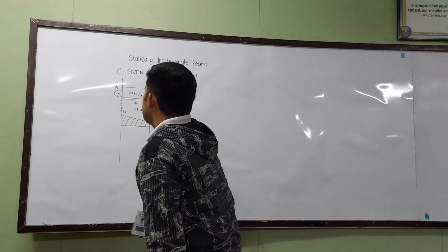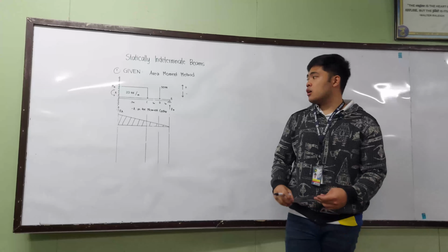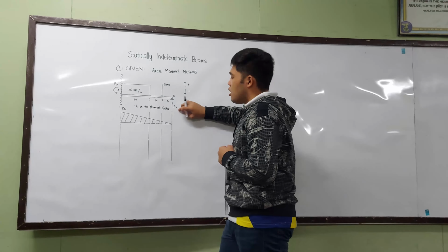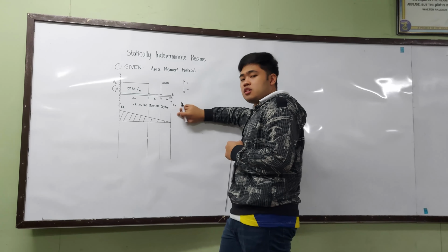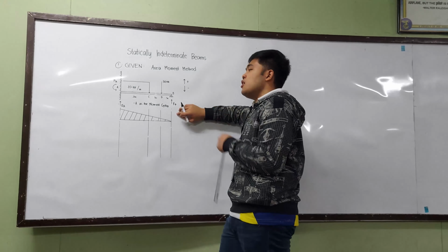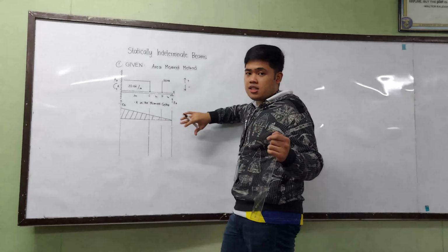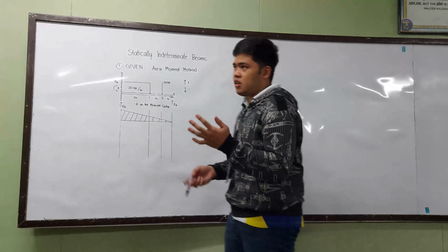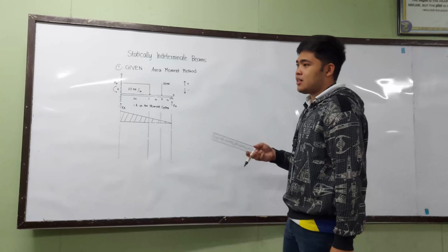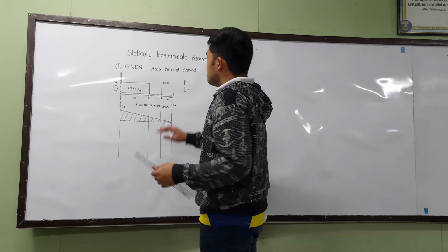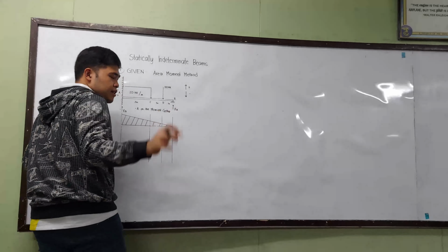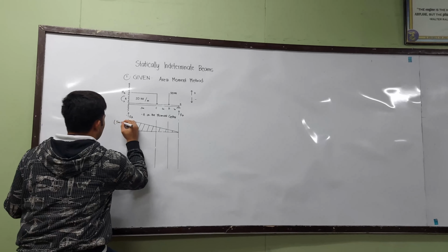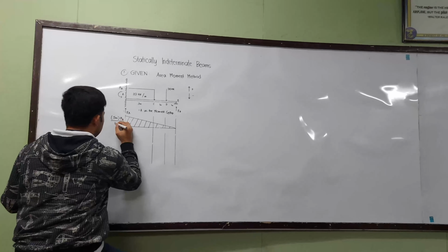Okay. So, point B, since we have RB, this is just force times distance, or distance times force. It's just the same. And all over EI, which is our constant that we will be using for today. Okay, so gagamitin natin lagi yung constant yun. So, anyways, i-eliminate din naman natin yun pagdating sa solution part. Okay, so we have force and distance, this times our force. So we have 5 meters. It's R all over our constant of EI.